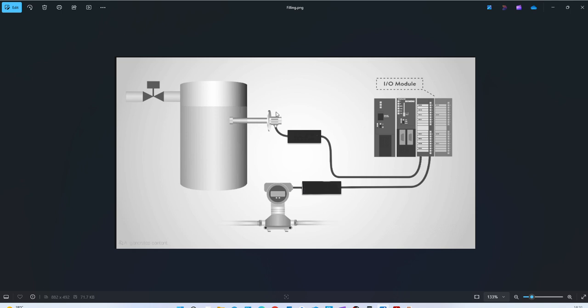So we're gonna do analog input, so that would be for the reading, and for us to operate the actuator, we'll be just using a digital signal to open and close. We're not gonna do positioning and half close, half open, but something like that. So we're gonna do full open, full close. So we'll open if the tank is at 20%, and then we're gonna close the actuator when the tank reaches 80%, for instance.